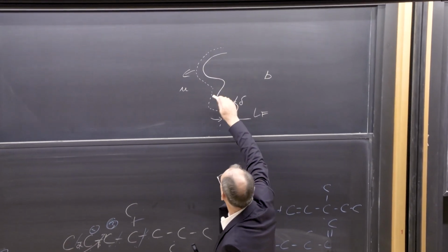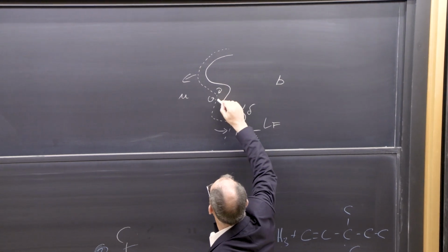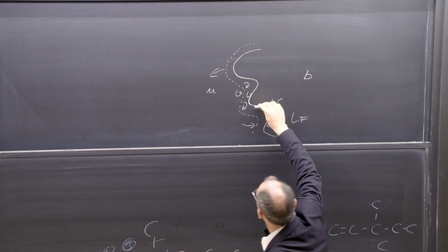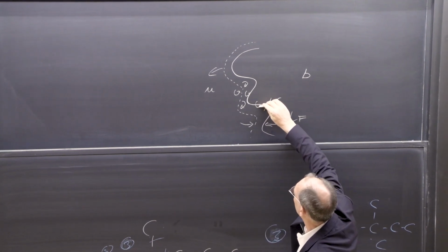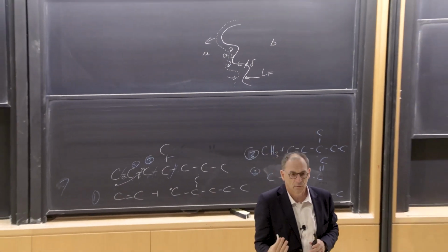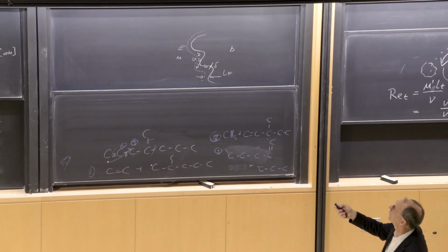And then I have Kolmogorov eddies, which are kind of this size. So they go into the preheat region. They mix in the preheat region, but they can just corrugate the reaction zone, but they cannot enter the reaction zone, okay? So that's what we call the thin reaction zones regime.